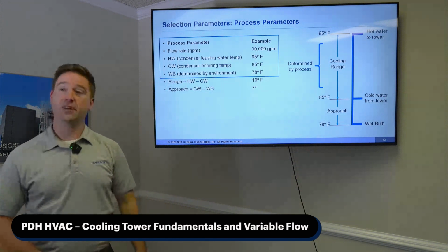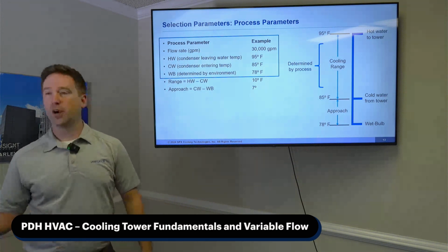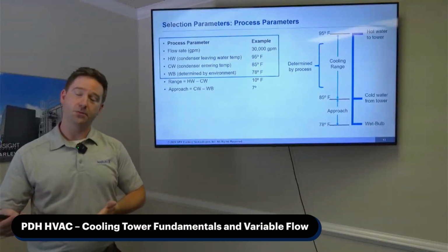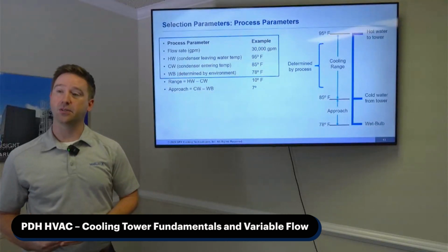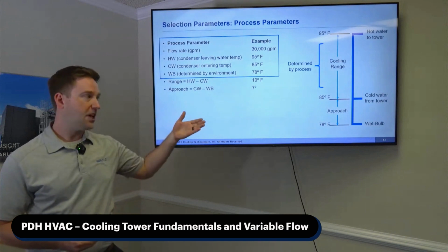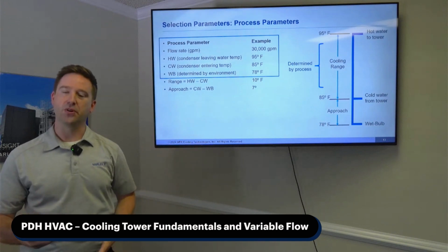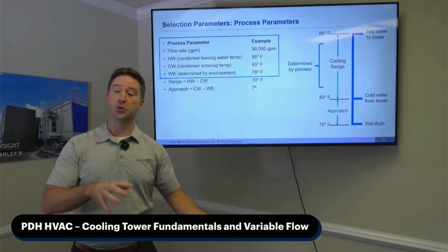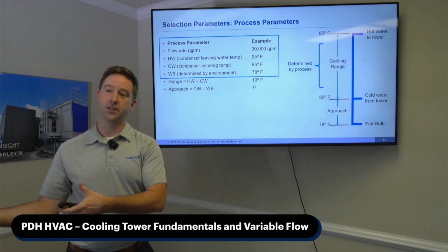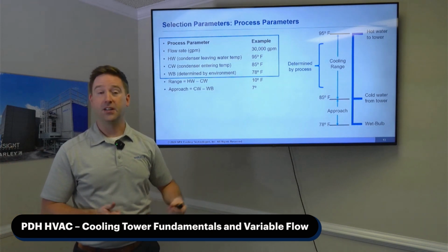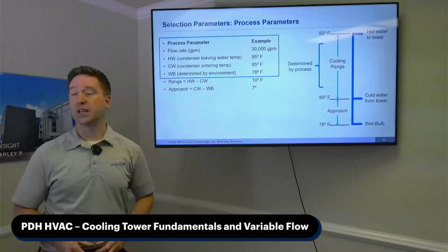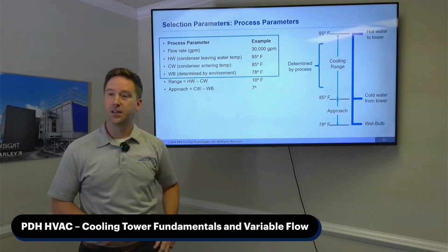That can vary depending on what your chiller requirements are. So there are some chillers out there that operate more efficiently, where they get a colder water coming back to them. We'll talk about this a little bit later, but you can actually oversize your tower a little bit to cool that water more to help your chiller operate more efficiently. It can save you energy. And if you design this whole thing up front, you can actually get a smaller chiller and save a lot more upfront capital cost as well. Great. Thank you. Yep.